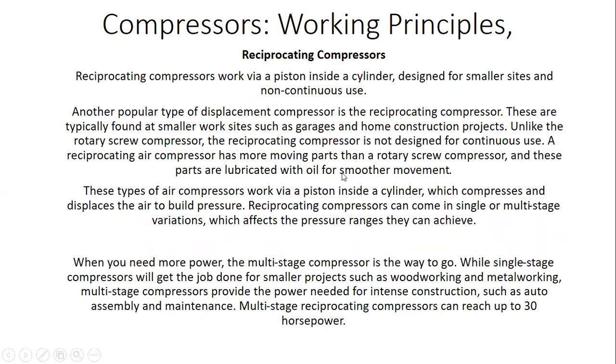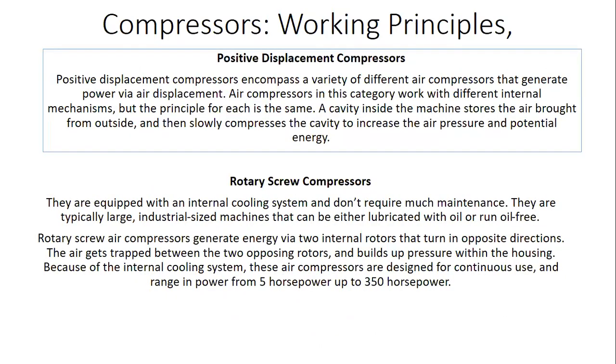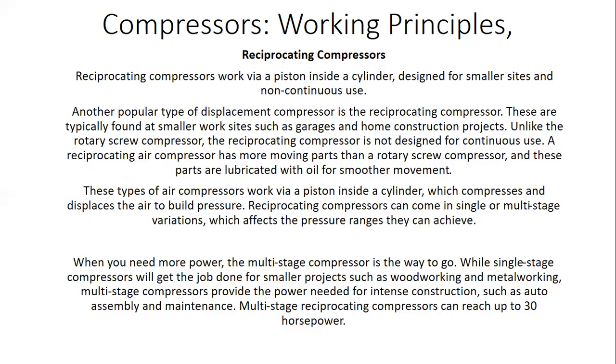Now, there's what is called the reciprocating compressors. These work via a piston inside a cylinder, designed for smaller sites and non-continuous use. Reciprocating compressors are not usually used continuously, unlike the rotary screw compressor that we saw in the previous slide. Here, it's also a displacement compressor, and they're usually used for small sites.